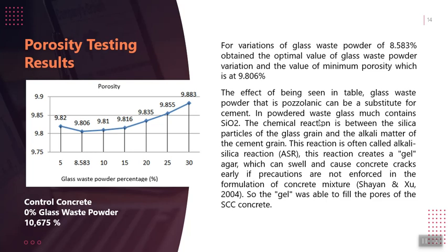Glass powder contains much silica. The chemical reaction is between the silica particles of the glass grain and the alkali matter of the cement grain. This reaction is called the alkali-silica reaction. This reaction creates a gel which can swell and cause concrete cracks if precautions are not taken in the formation of the concrete mixture, according to Shayan and Xu in 2004. So the gel was able to fill the pores of the self-compacting concrete.